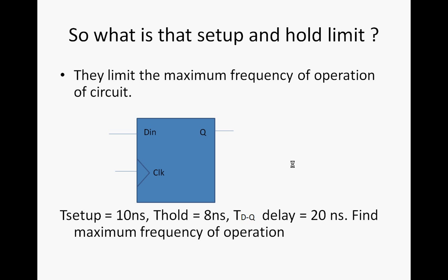They obviously give an undesired mode of operation, but also, the maximum frequency of operation is limited. If my input signal is changing very fast, my circuit can't see the input changing at that frequency. So it basically limits the maximum frequency of operation of the circuit.